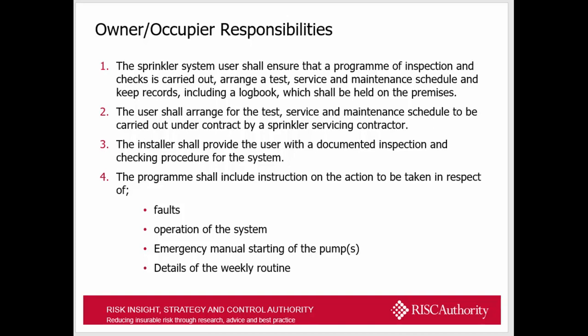The installer should provide the user with documented inspection and checking procedure for the system. So when a sprinkler system has been installed, they should be provided this information. They should be trained so they understand the system. And the programme shall include instructions on the actions to be taken, such as faults, operation of the system, emergency starts of the pumps, or details of the weekly routine.